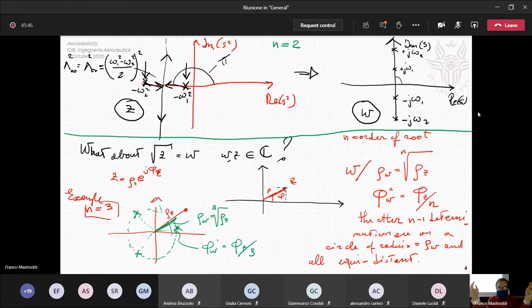Whenever lambda is increasing, the amplitude of omega 2 is decreasing, and the amplitude of omega 1 is increasing. And therefore, what happens, excuse me, I was wrong before, I'm sorry. What is happening is that this is going higher and higher with the same phase equal to pi/2. This is higher and higher negatively with a phase equal to minus pi/2.